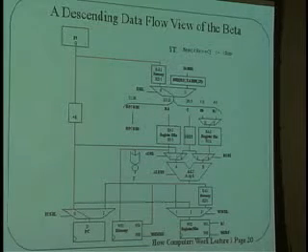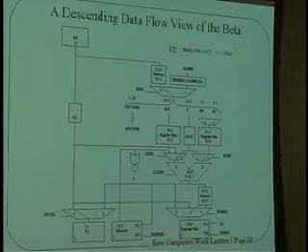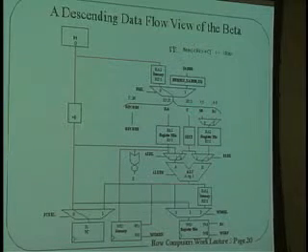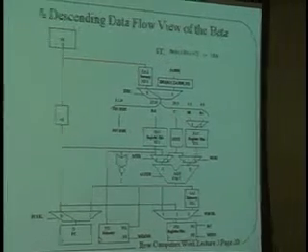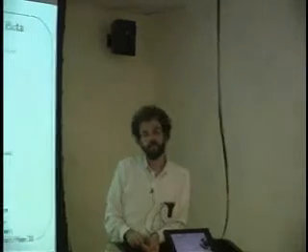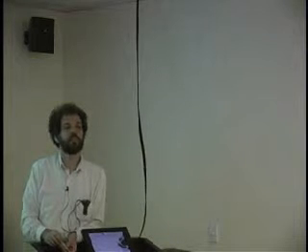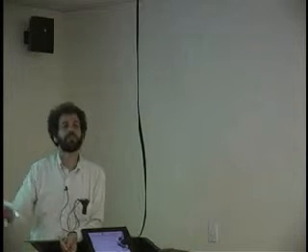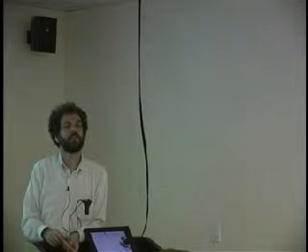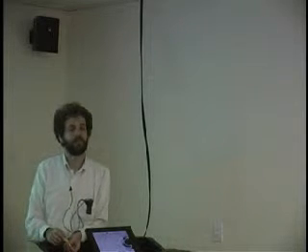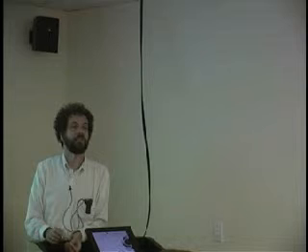And what that instruction is going to do is say stop what you're doing and jump to the location XADDR. Do a branch to there, and remember where you came from in XP. That's called an interrupt or an exception, and it basically is a way of stopping the processor along its path and suddenly doing something else because some perhaps disastrous thing has taken place. One example is if the code is running along and it divides by 0. In general, that's a bad thing and you want to stop, right?